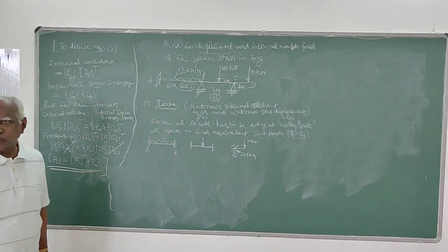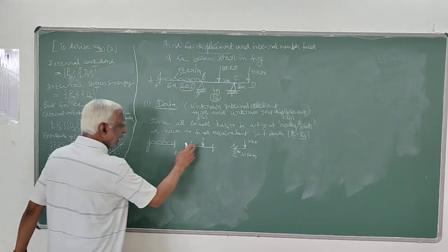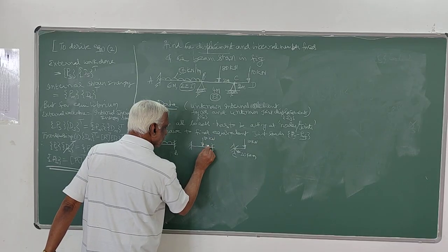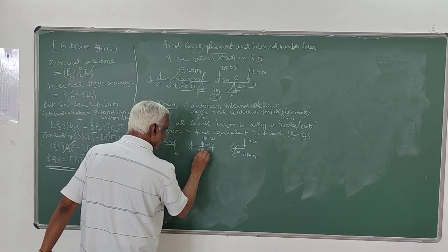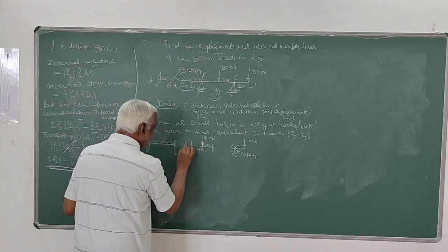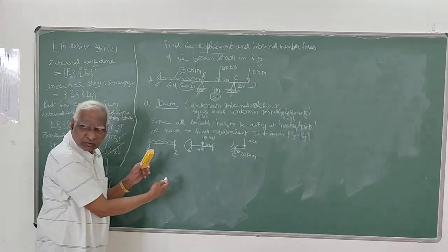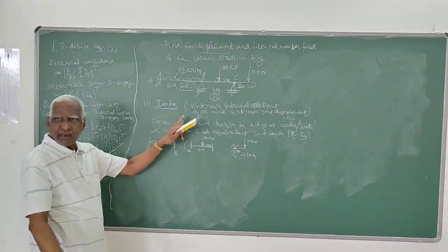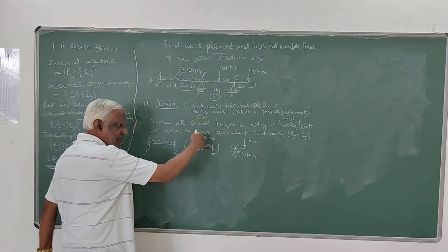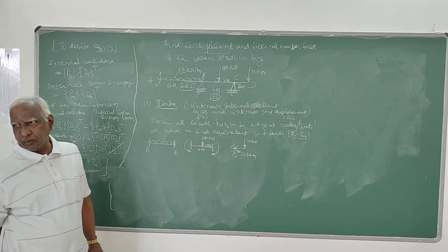It is 20 kilonewton per meter at C. Now here, this is 80 kilonewtons, this is 2 meters, this is 4 meters. So the end moment will be anti-clockwise here because the applied moment is clockwise, suggesting it will be anti-clockwise. Here it will be clockwise, the applied moment being anti-clockwise, so the reaction should be opposite to that.